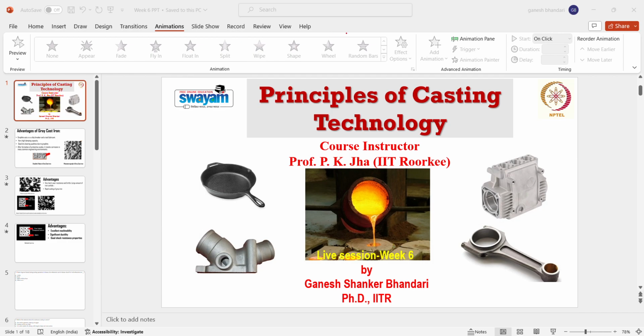One phase is iron carbide, which is Fe3C. That is also a metastable phase, because according to your process, whether annealing, quenching or austempering, that iron carbide phase is going to convert. When we are talking about annealing, we are talking about very slow cooling.